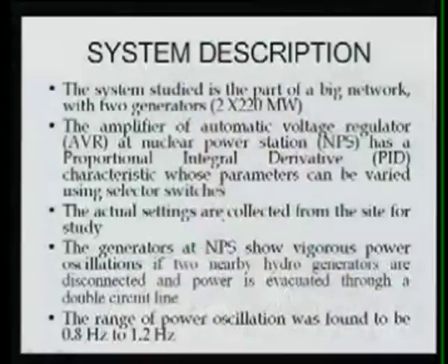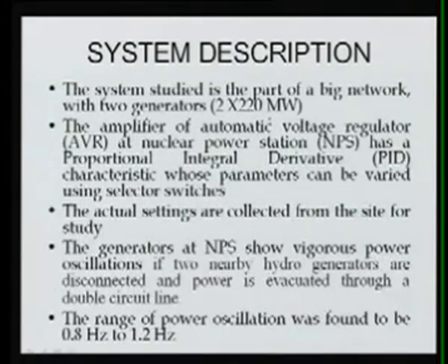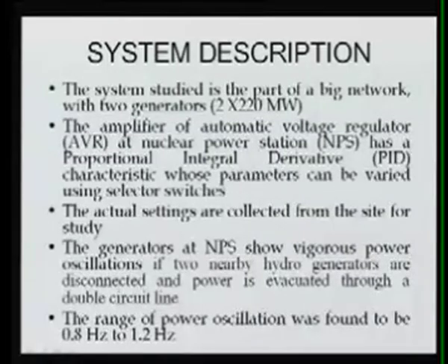Here we studied this system, and finally we found this was due to the proper tuning of the power system stabilizers. The system studied is part of a big network, of course the whole southern region, and we took only a small portion of the system where the two generators near Kaiga have been considered.